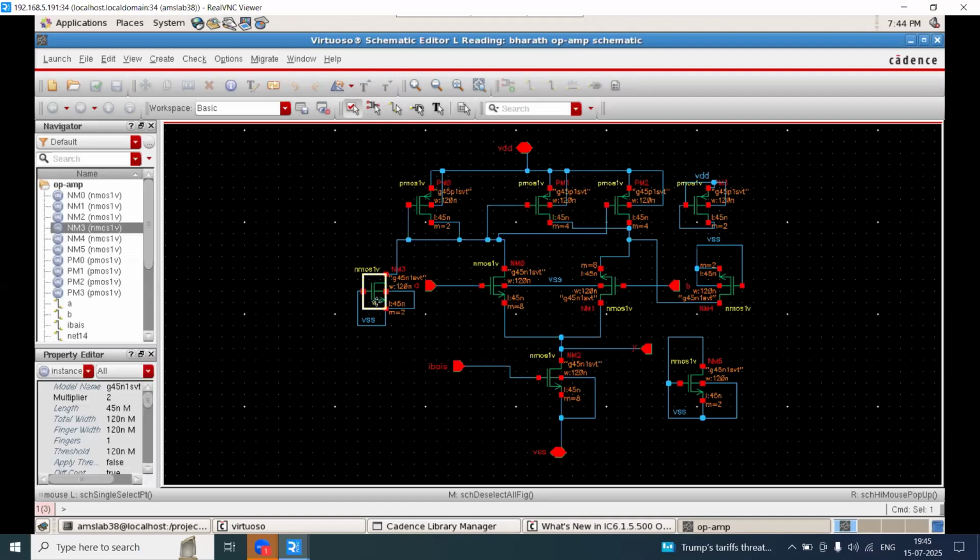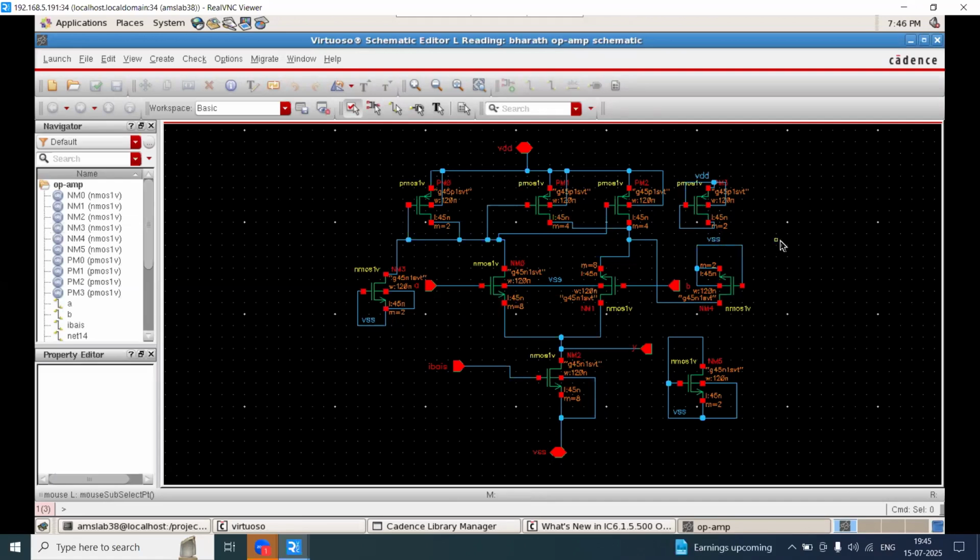This one is a half dummy or signal dummy, which is going to share this net commonly. One side signal is coming, so that will be connected to the signal dummy. Why do we need these dummy devices? These dummies are used to protect the active devices, so as not to have an effect on the active poly gates. In general, in FinFET and others, we use stack dummies, series stack dummies.